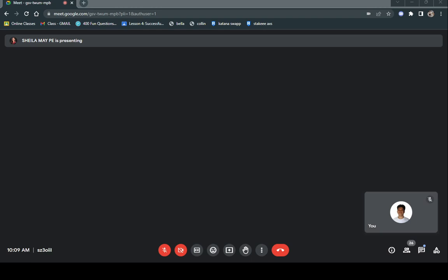Letter C, we need to find VDS. Okay, VDS, VDD minus ID times RD plus RS.